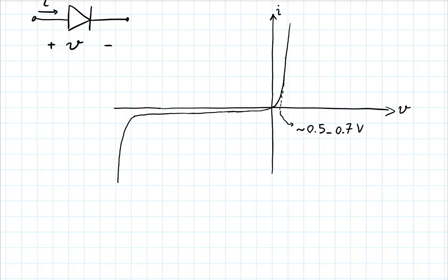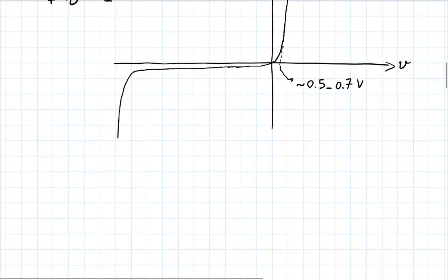Now, this reverse current, on the other hand: if you give it a negative voltage, you will see that it does give some current, but it's a small amount. For many applications, you want this amount to be really small, because if you think about the switching behavior that I just described, ideally you would like this to be 0, right? Not have any current on this side. That depends on the exact design of the diode, but it could be something very small indeed. We could be talking picoamps, nanoamps, depending on how large it is and what material it's made of. OK? So this is a very small current.